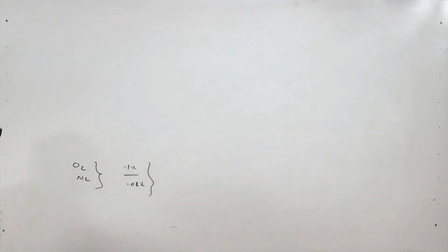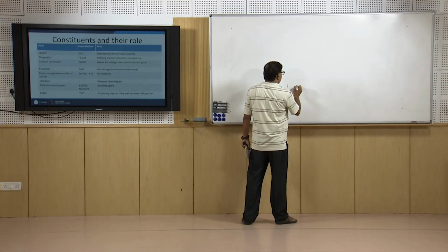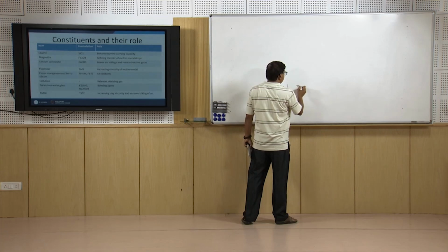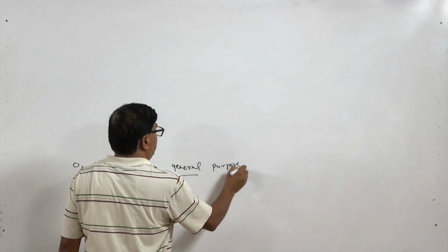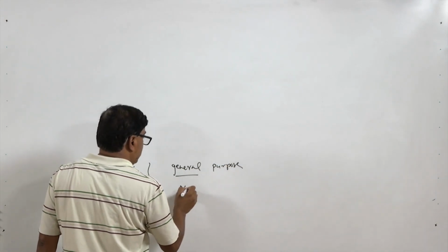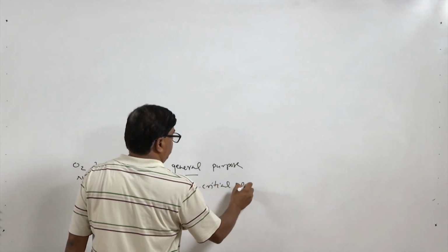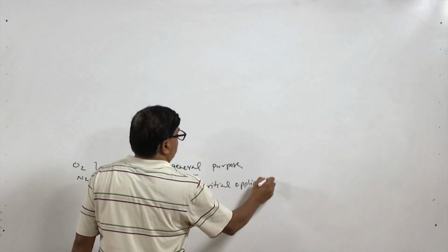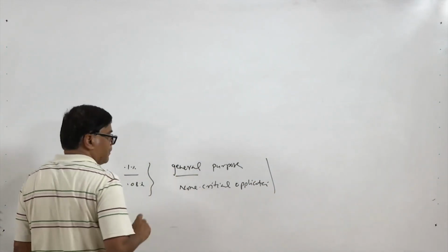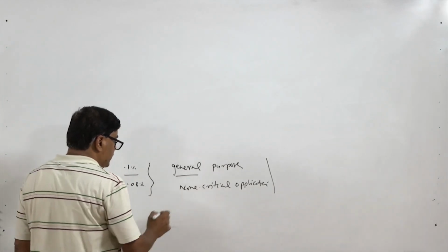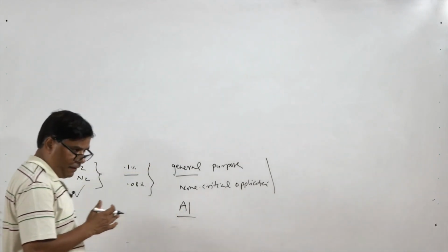the properties of the weld joint, and that is why shielded metal arc welding is good for general purpose welding, and wherever you see non-critical applications of the welding, because the quality of the weld joint is not that good, due to the higher concentration of the gases.